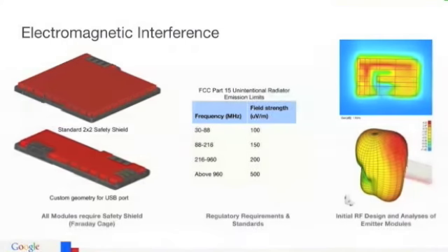Now, this serves two purposes. One, it prevents users from accidentally touching the sensitive components on the PCB, but it also provides a very convenient Faraday cage. So we've actually specified that the safety shield should be made of, I think, nickel or some other functionally equivalent metal.